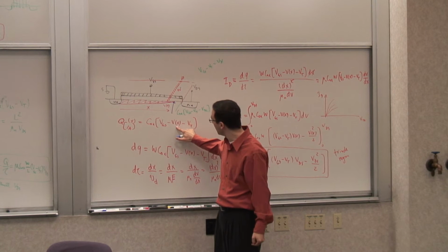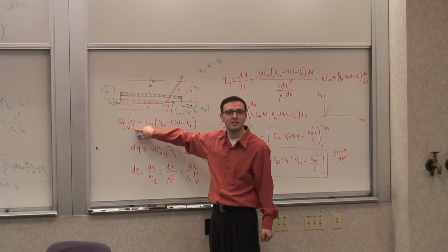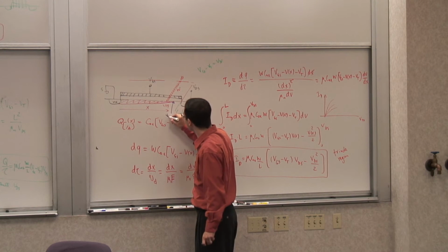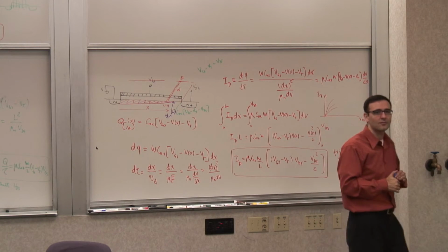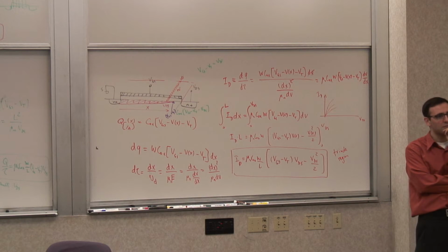If that voltage is VGS minus VT, the charge becomes 0. That's the verge of where it becomes 0. So the voltage at this point is always VGS minus VT. And that's something good to remember.